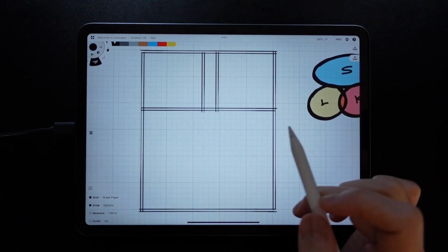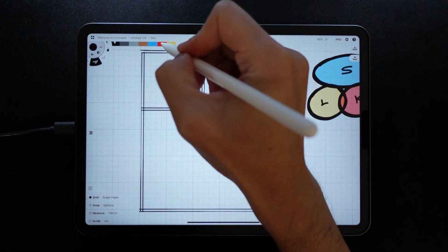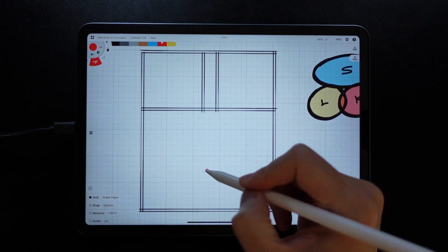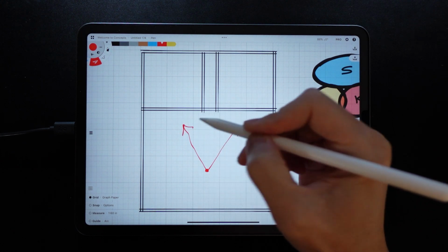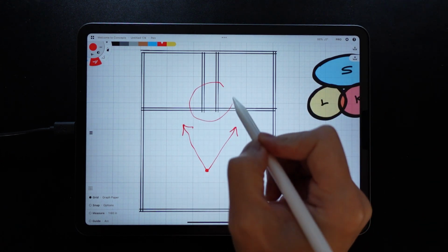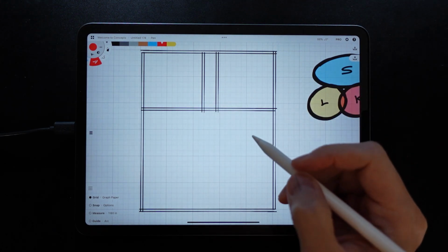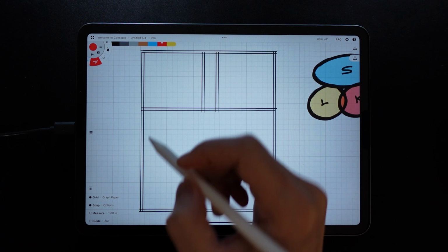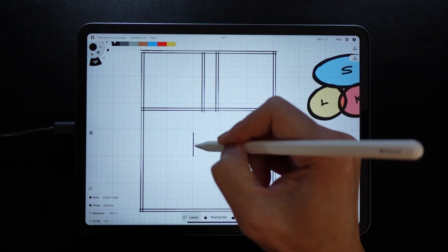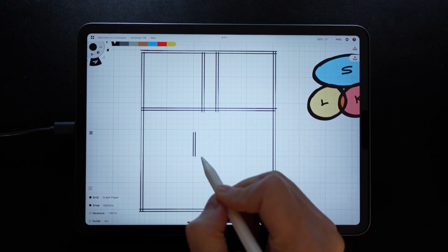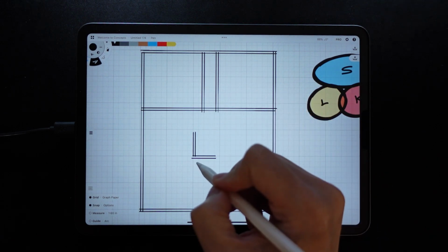Okay, so we have our 2 bedrooms right here and our closet in the middle, but I just want to show you something here. If someone is in the living area, their sideline is gonna be pointing directly towards the future bedroom doors. So what I recommend is to create a little transition space here, like a small hallway, to block the view from here. I'm gonna go ahead and create a small hallway. Here I'm gonna just add these 2 lines here. Okay, I'm just gonna create a hallway. Probably it's gonna be around 3.5 feet by 3.5 feet.